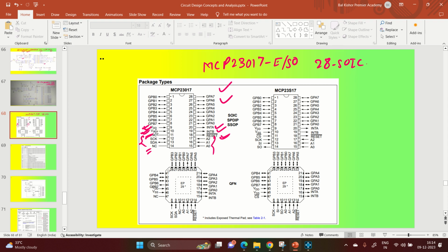You can see we have the VDD pin, that is the power supply pin, and the VSS pin, that is the ground pin. We have two non-connected pins, NC pin 11 and NC pin number 14, and we have two lines, the SCK line and the SDA line, which are our interest, the I2C lines. We will be communicating through these for whatever position we want on all the IOs. You can see port A is 8 pins and port B is also 8 pins.